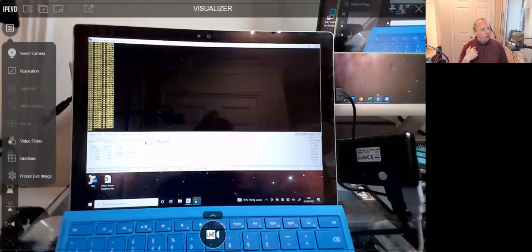And I tell you, I've been spending the last 2 weeks doing some EMC work, and the amount of people I see there, whenever they've got data streaming off a product that they're testing, they're always using RealTerm or PuTTY or any of these other very simple UART interfaces. So you don't need anything fancy, and it takes hardly any electronics and next to no memory, which is always a good thing.